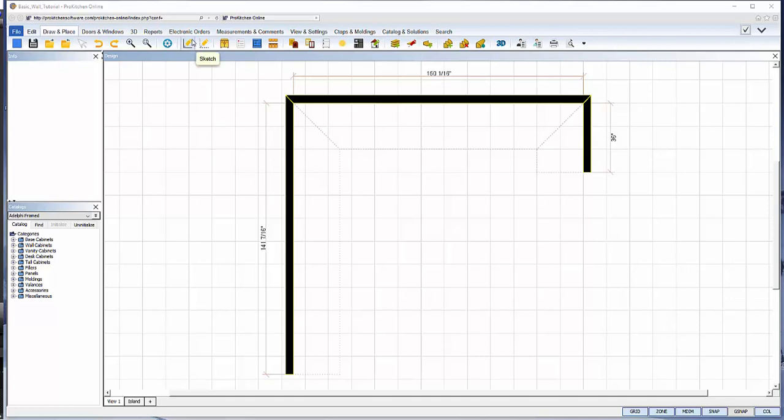I have a 44-inch doorway next to another 36-inch wall, so I'll click on the Sketch Wall icon on my toolbar near my 36-inch wall so the measurement tool appears and set the length to 44. Make sure my thickness is 4, tab to height, and hit Enter to set my measurements. My sketch tool is still turned on and expecting to draw a wall, so I'll head it to the right direction. Again, set my measurements in the info box. Length is 36, my angle is 270, angles are also measured clockwise.